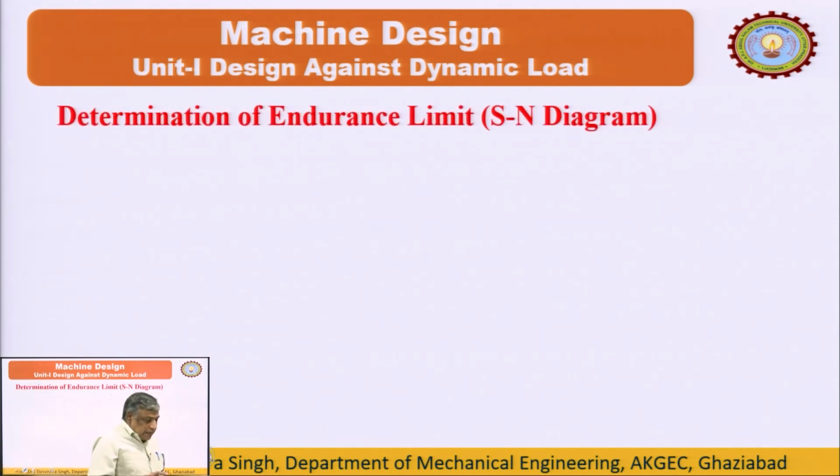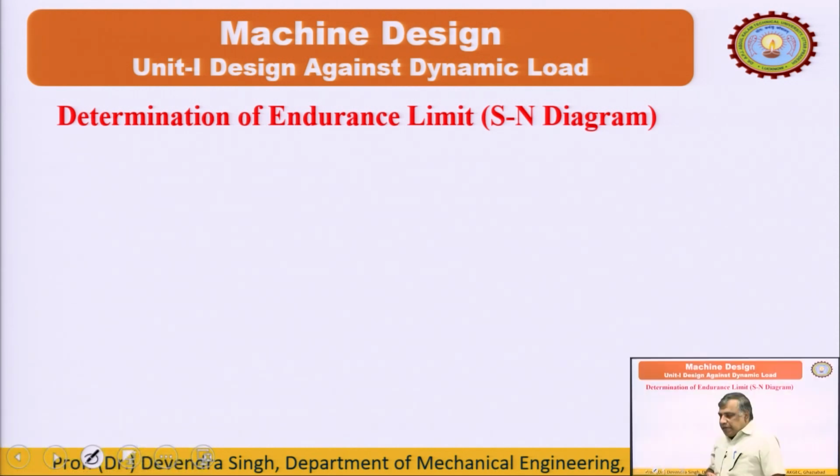So against static load, when we design, we consider the true strength, that is the yield point in tension and ultimate tensile strength. These are the failure stresses or the strength of the material, and if we want to include some reserve strength, then we have introduced the factor of safety. Here also factor of safety remains same, but for designing the components against the dynamic load, a new strength will come into the picture, and that is called the endurance limit.